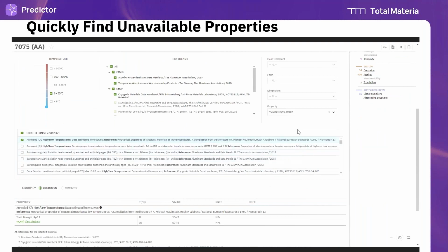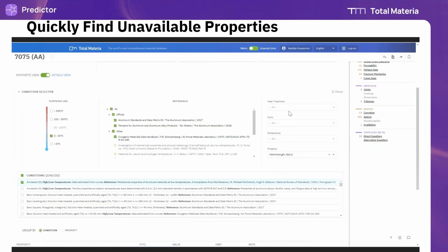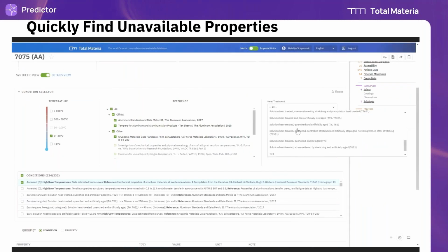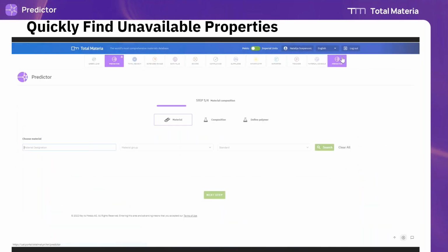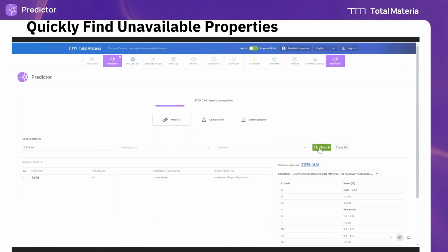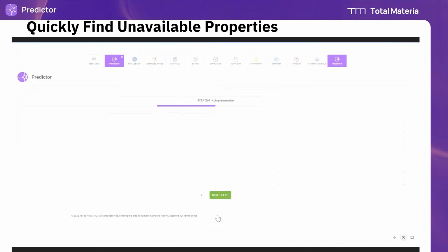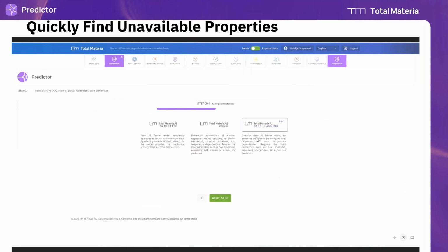A lot of information, but what you want to see is the yield strength value, but for T8. We have hundreds and tens of different heat treated 7075, but T8 is not available. Nobody tested the material that way, so we don't have it. Nobody does.